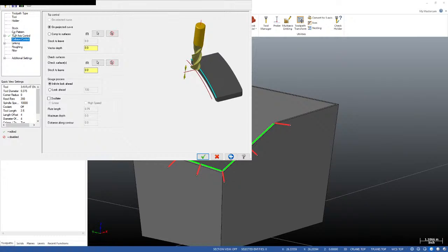In the case of compensating to some kind of organic surfaced shape, you would use collision control to choose surfaces you wanted the tip of your tool to be tangent to, but we are keeping those processes separate. We're divorcing them, right? There's the tip control, which can be influenced by your cut pattern, but it's not the same thing as your cut pattern. It's an important distinction to make.